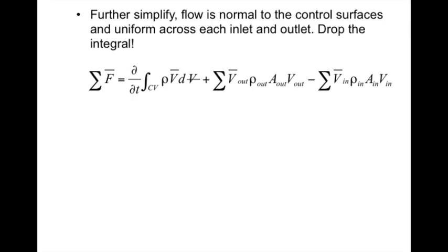And this is a good place, as I'm taking a closer look at that form of the equation, to point out some of the terms and think about how this all builds upon each other. The first one I want us to focus on is that over here with our outlet, and same thing with our inlet, we have an area and we're multiplying it by a velocity. And hopefully you see that now and think, wow, that's something we've seen before when we dealt with the continuity equation. That's the volume flow rate, right, that we represented with a Q. So that might have units of meters cubed per second or feet cubed per second.